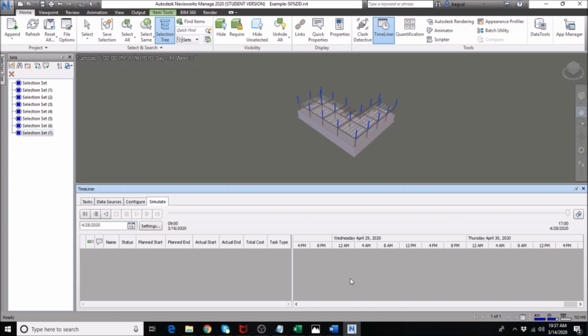column as well too. So here, what I'm going to do in most cases, especially for those structural steel, what they usually do is to construct all the framing first, and then they go back. Once they build the framing at the next level, some they put in the decking on the previous level and they move up. Others, they usually complete the entire framing for the structure, particularly for steel structures. Okay, that is different if there is a reinforced concrete, which they create a deck at every given level.